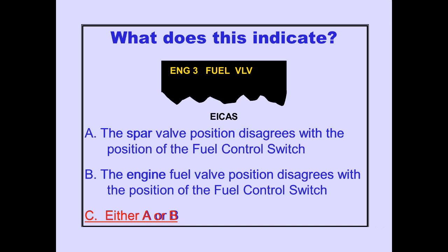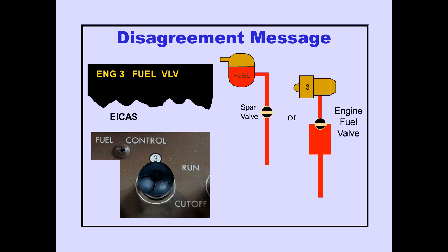Answer C is correct. The engine fuel valve message is a disagreement message for the spar valve or the engine fuel valve and the fuel control switch.